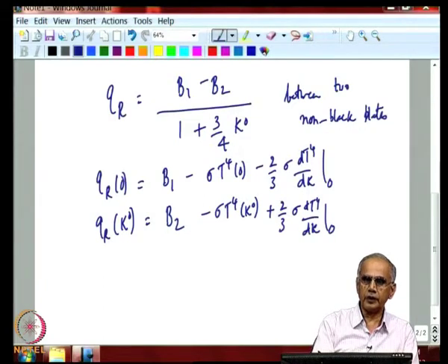In radiation, we have to invoke it, because unless it is in the optically thick regime, generally there is a temperature difference between the gas layers next to the wall and the wall temperature. Although the temperature is not continuous between the gas and the wall, fluxes are continuous.